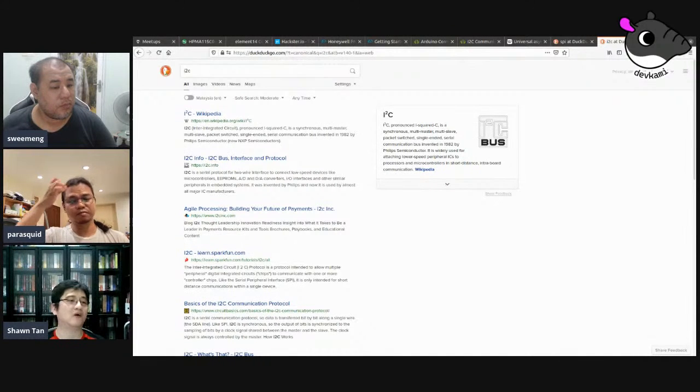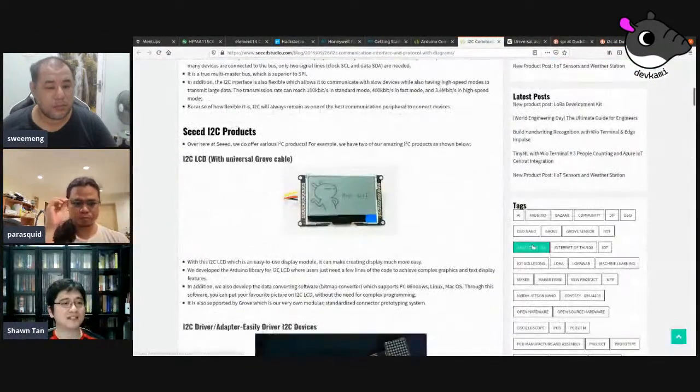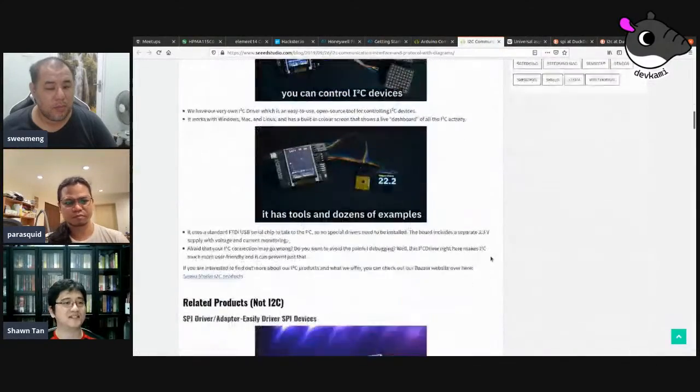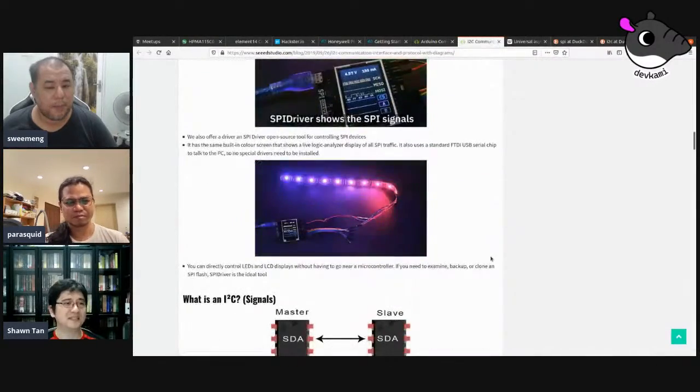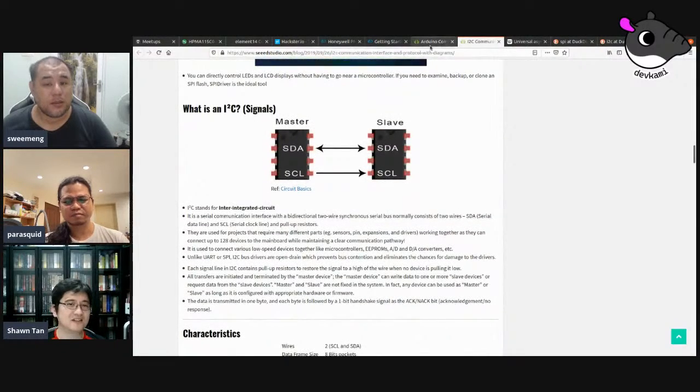So at maximum, you can have about 1,000 devices on a single bus, addressable from a single bus. But like I said, with only 100 kilobits, if you have 1,000 devices, that's only like 100 bits per device per second. It is unlikely for that to happen. It's going to be very slow.